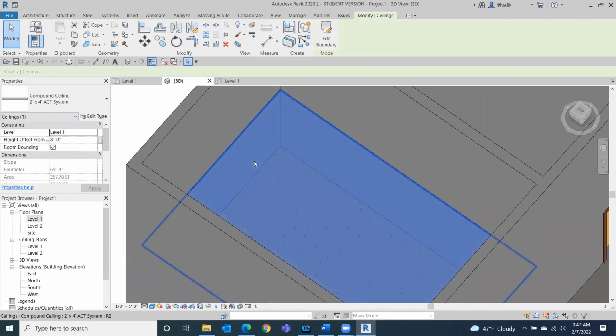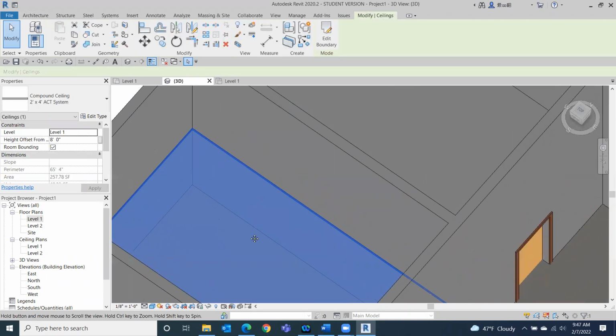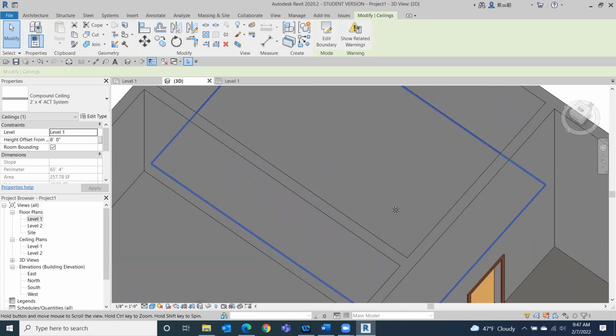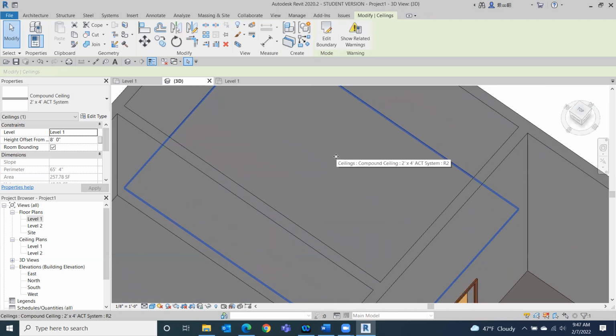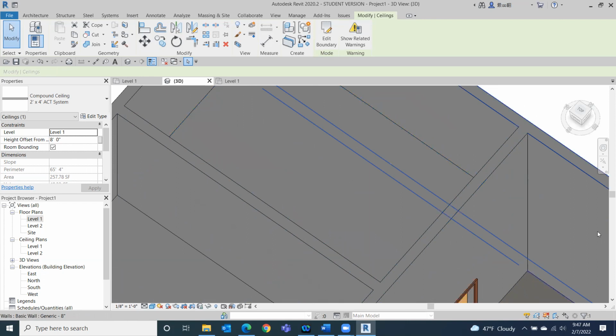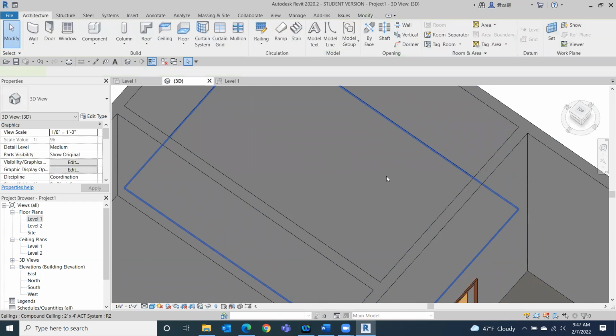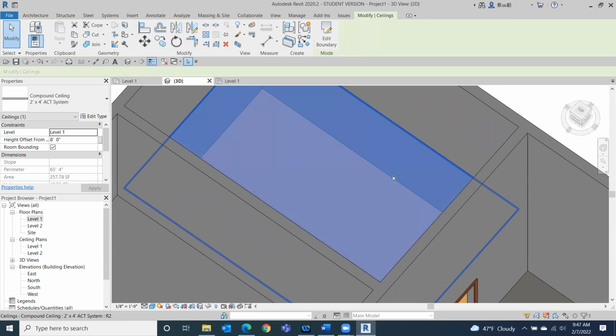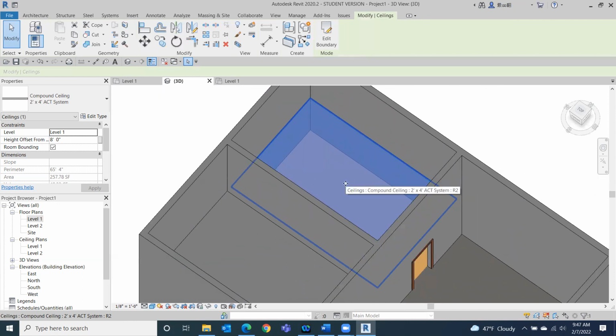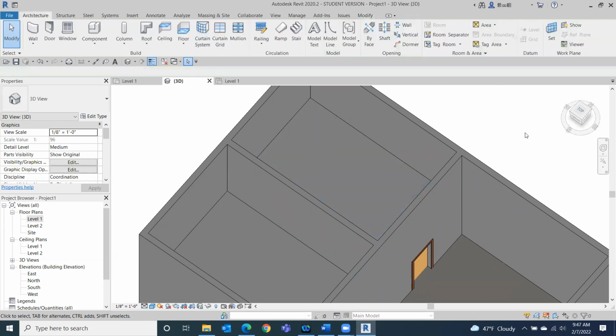When I click off of that, I can see inside, so I know there's one ceiling in place. Over here, I know there's multiple ceilings in place because when I click on it, make it active, I can't see through this. And if I hit delete, now I can see through, so I know that there's only one ceiling in place. So that's probably the biggest confusion, is people putting their ceilings in the wrong level.